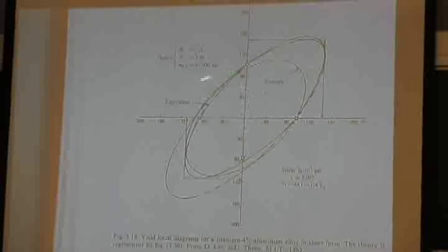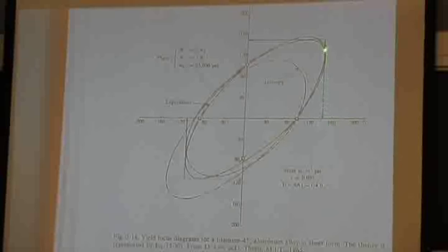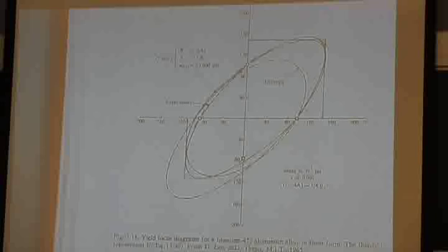Anyway, so Dion was looking at alpha titanium sheet, which had a uniaxial yield strength of 95 KSI right here. Isotropy is this dashed ellipse here. If he actually did biaxial stretching, which he did in the laboratory, he could get biaxial stretching strengths up to 145 KSI. So it really makes a difference. This is not a small change, okay? This is real material here.